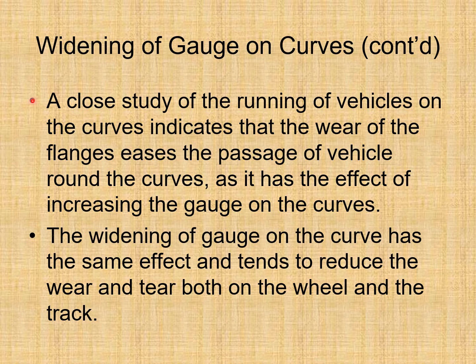A case study of the running of vehicles on the curves indicates that the wear of the flanges eases the passage of vehicle round the curves, as it has the effect of increasing the gauge on the curves. I will repeat, this is a very important point: a close study of the running of vehicles on the curves indicates that the wear of the flanges eases the passage of vehicle around the curves, as it has the effect of increasing the gauge on the curves.